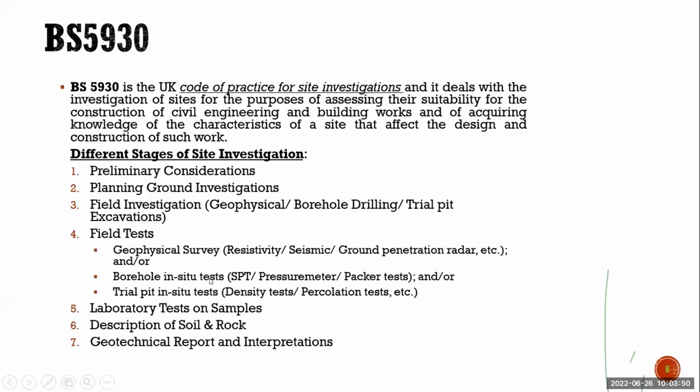What are the field tests? I already talked about the geophysical survey. It can be resistivity test, seismic method, or ground penetrating radar, etc. Other methods are also there. Then borehole in-situ tests. A borehole in-situ test can be SPT, standard penetration test, pressure meter test, packer test, and we have other methods like cone penetration test and dynamic cone penetration test. We will see these in the next few slides.